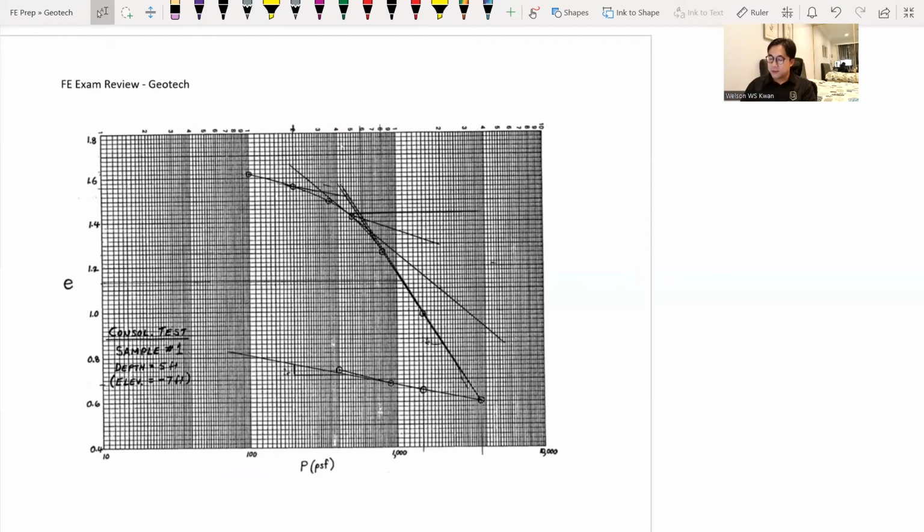And from these lab results, the Casagrande construction has already been performed. For the details, you can go back to ASTM manuals or my CE366 lecture at Cal State LA, the detailed Casagrande construction method. But here, in short, this is the point right there that represents the maximum past pressure.